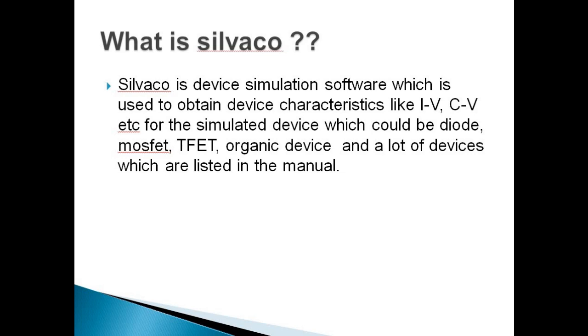Silvaco is a device simulation software which is used to obtain device characteristics like IV, CV, capacitance-voltage, current-voltage characteristics for the simulated device, which could be a diode, MOSFET, TFET, organic device, and a lot of other devices which are listed in the manual. The software comes with a set of examples which are listed in the manual, which were already discussed in the last presentation. At the end of this session, you should understand the basic flow of writing code in DeckBuild and build your own structure whenever required.